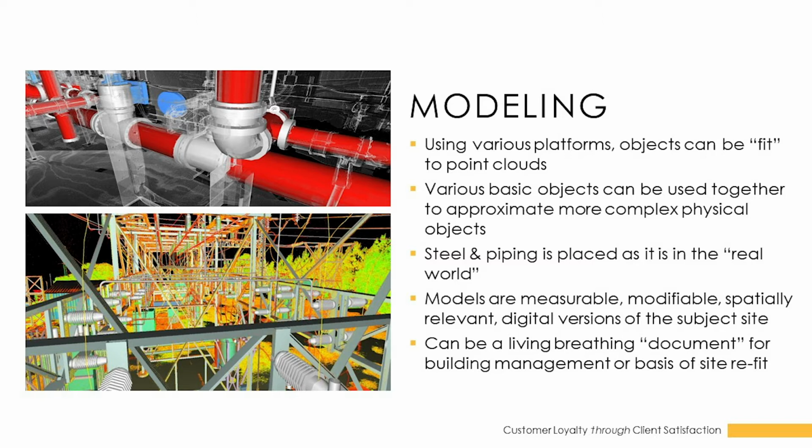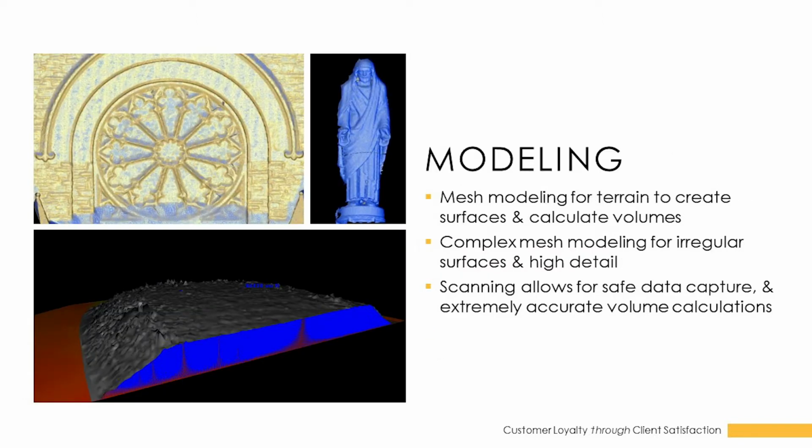So a more specialized version of modeling off of the point cloud is mesh modeling. Mesh modeling is very useful for a variety of applications. I would say some of the more understandable applications would be to use meshes to create surfaces that would go into Civil 3D, or use them as metadata going into a surface in Civil 3D. One of the more important applications of using a mesh in a surfacing fashion is for doing volumes.